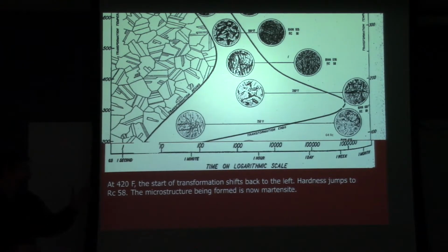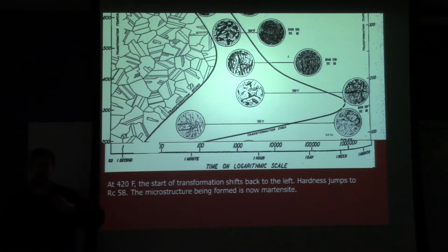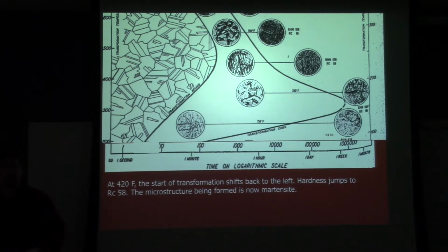But you might do more of the austempering kind of situation, not necessarily with the goal of forming bainite. You might be trying to form martensite, but you might be trying to prevent, say, cracking in a part. If you've got a part that is a large component and it has a big delta T between the surface and the center, you might do something like the austempering type of approach to allow the part to come to a more uniform temperature at some intermediate spot, and then finish the cooling. We do this on occasion in the big forgings that we make, because otherwise we would have significant risk that they would crack.